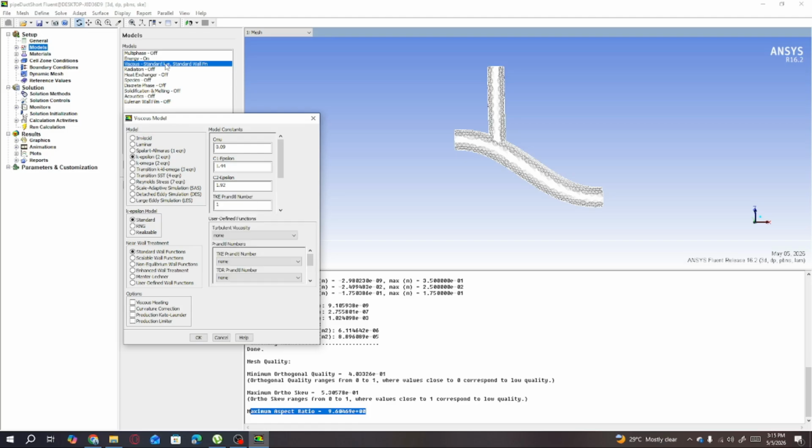One more thing I want to add is that if we are selecting the k epsilon model, we can also modify its model constants, if we want to validate our results and they are not matching with our exact results. So CFD is not all about simulating the case. It's all about understanding how smartly you can get realistic data from the simulation.